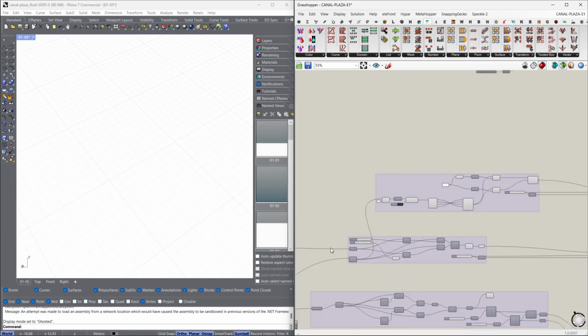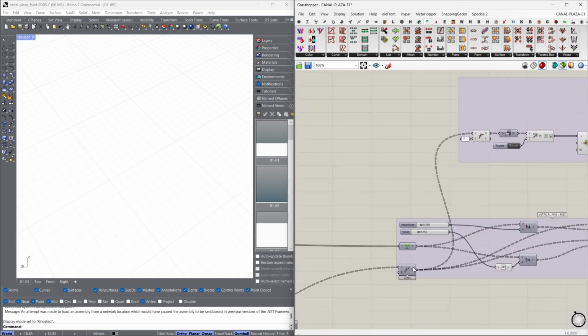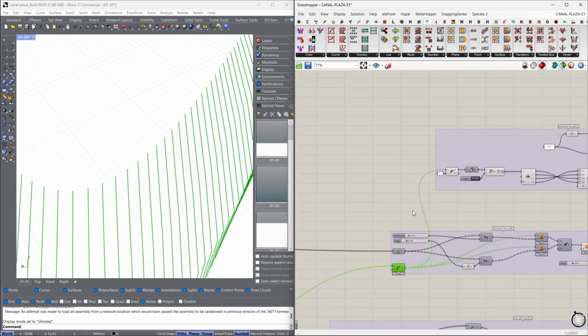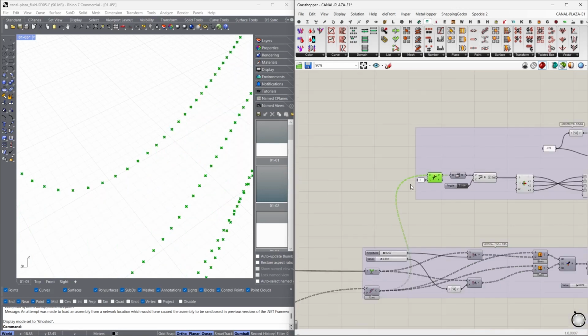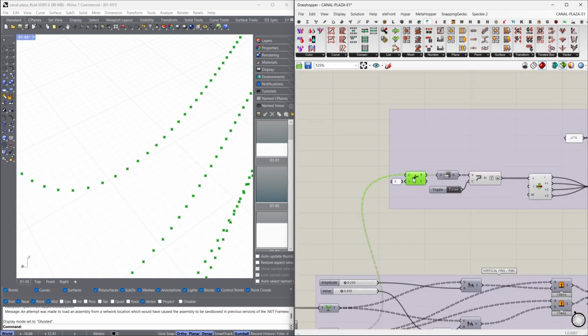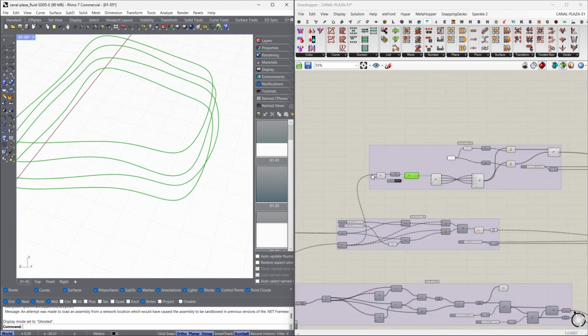And then the top component, I could have used our base geometry right up front, but I just took the ribs we created, used a Discontinuity component just to get the points over there, flipped the matrix again so we're working horizontally, and then created this whole continuous curve for each floor.